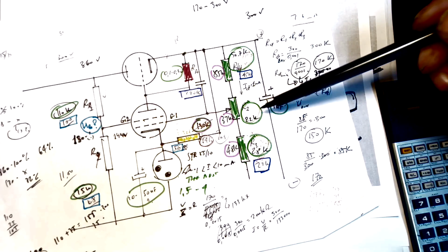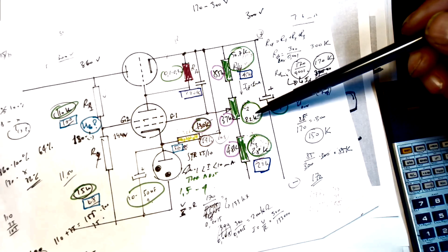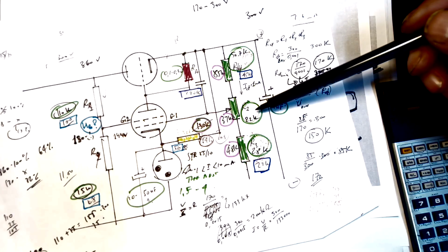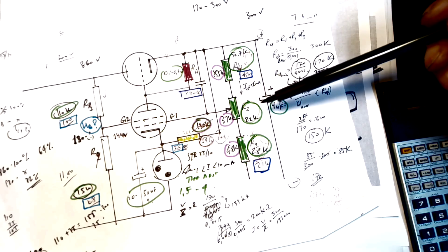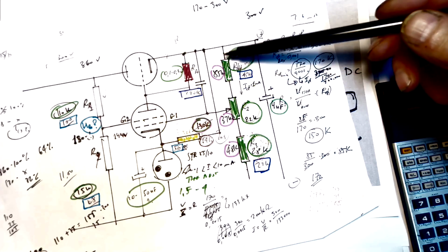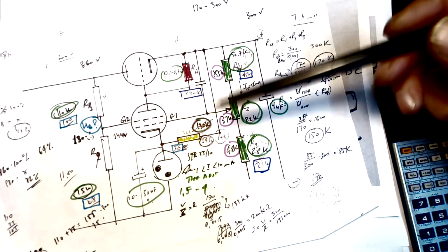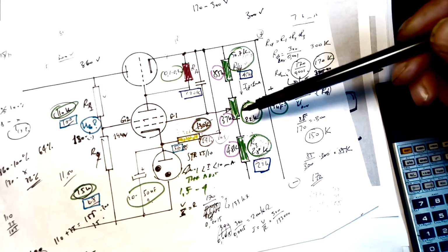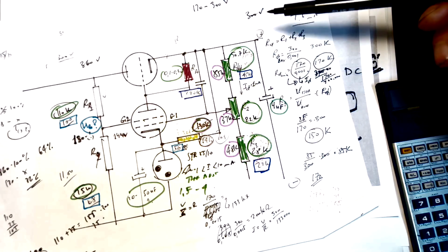And finally, when I started measuring, the pot shows it's not 22. It's only written on it 22, but it was 24.5. With resistors, we can also always assemble resistors by connecting them in parallel, etc., and it's okay.